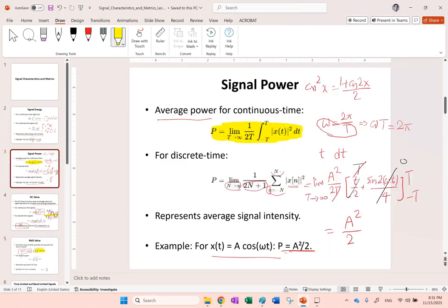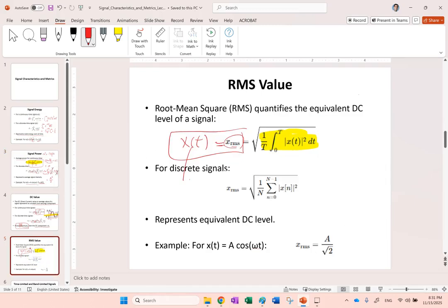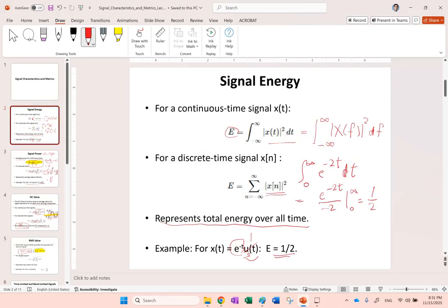Look at that. That's the same thing, except for integrating it from negative t to t and dividing by 2t, or integrating it from 0 to t and dividing by t. That's the same thing. So this guy here is exactly what you see under that square root, right? And you know that if your signal is just a constant x RMS, the power of that signal, or the energy of the signal for that matter, is going to be the value squared. So the energy of fixed x RMS is simply going to be x RMS squared, because you only have a single value.